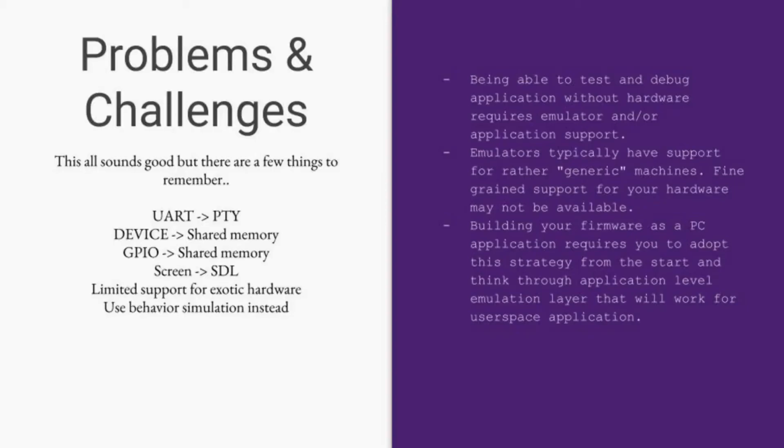So what are the problems and challenges with this? Well, the biggest problem is that you don't have really good support for exotic hardware on emulation. And even if you're compiling for a POSIX target, you have to think about that from the beginning of the project. It's really hard to implement this portability later in the project.